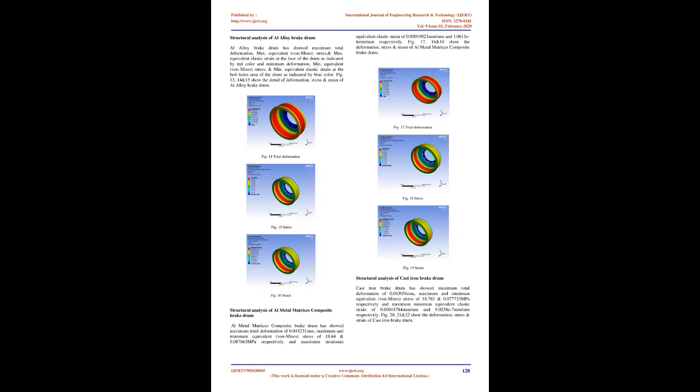Theoretically, the heat generated during braking is designed to be absorbed by the drum in the process of conduction and by the surrounding air in the process of convection. Some amount of heat is dissipated by radiation from the brake system. Poor design and low quality of materials of the truck drum brake are insufficient to handle continuous brake application because of rapid wear and low thermal dissipation, which then increases the drum temperature and causes early fade of brake.